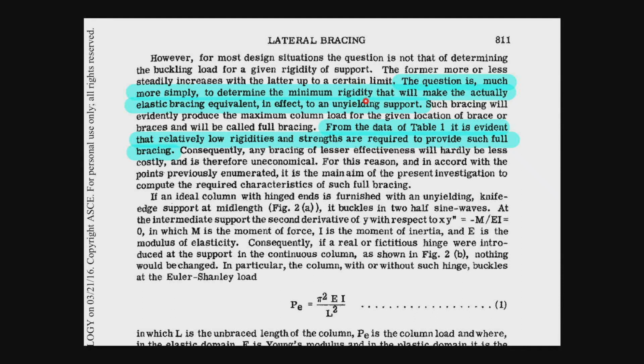You don't want to put too much. That will make the actually elastic bracing equivalent in effect to the unyielding supported support. Such bracing will evidently produce maximum column load for the given location of brace or braces and will be called the full bracing. Yeah, this is the condition that is desirable.